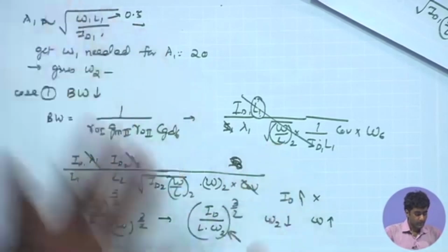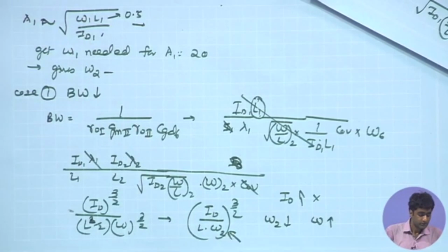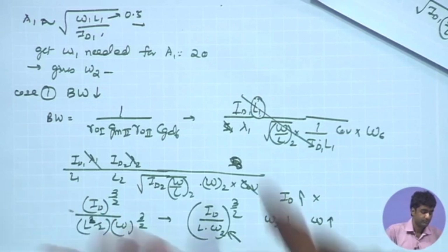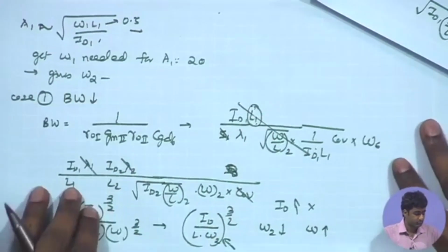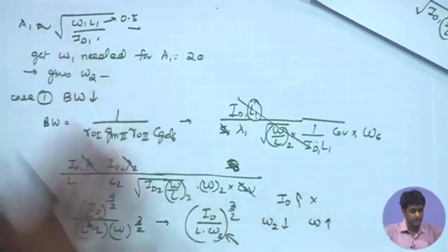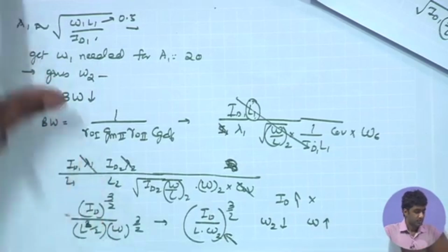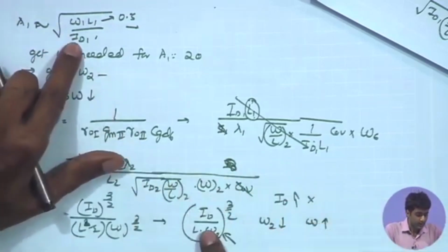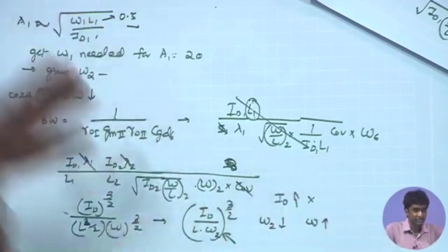Now if we are able to do that, another target would be that we would like to reduce the bias current also as much as possible, so that the gain and bandwidth both are maintained while achieving limited power consumption in the amplifier. So for that we can see once again these two operations. If you have to lower the power, suppose we have achieved this appropriate bifurcation between A1 and A2, so that the overall gain and bandwidth is now being met. Now if that is being met, the other target is to check whether we can reduce ID further. So again these two equations are going to give me some direction regarding that.